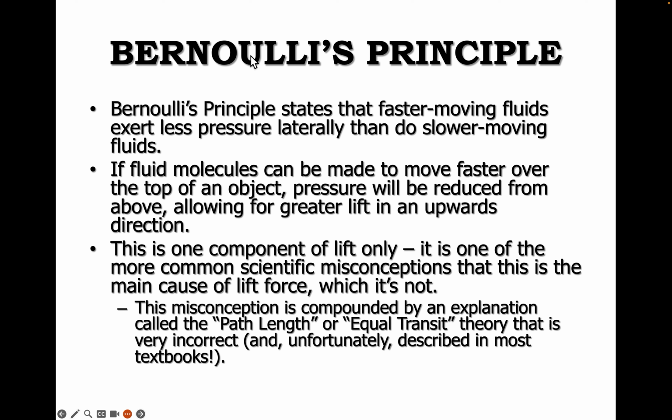Okay. So in order to understand lift force, we need to understand Bernoulli's principle. What Bernoulli's principle says is that faster moving fluids will exert less pressure laterally than slower moving fluids. Essentially, faster fluid, less pressure. Slower fluid, more pressure. If fluid molecules are made to move faster over the top of an object, pressure will be reduced from above, allowing for greater lift in an upwards direction.